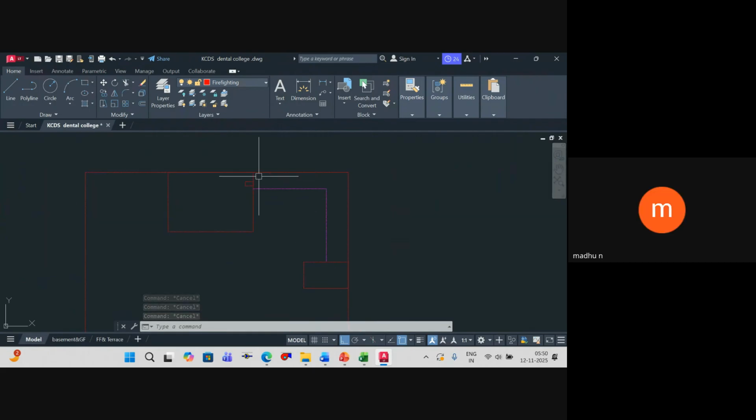What is the limitation of the travel distance from the staircase to the pump room? Is there any limitation on the travel distance? See, in any building you should reach within 30 meters. Sorry, within 45 meters you should reach any building at the end of the day. It should be within 45, is it? Yeah, your fire exit staircases should always be designed within 45 meters distance.